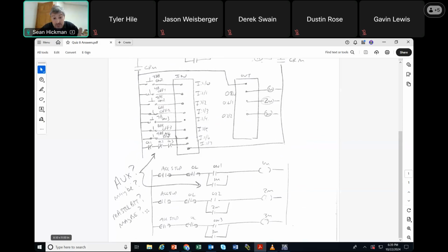Maybe a master bit, didn't need it, but a lot of people put the master bit, which I thought was great. You know, you just had a rung that started, and if the master stopped or any of the overloads went down, the master bit went down, and the master bit was on each rung. That wasn't bad. Just a few different ways to do this, but overall, generally pretty good. So I put my overloads on the master since some people did that.